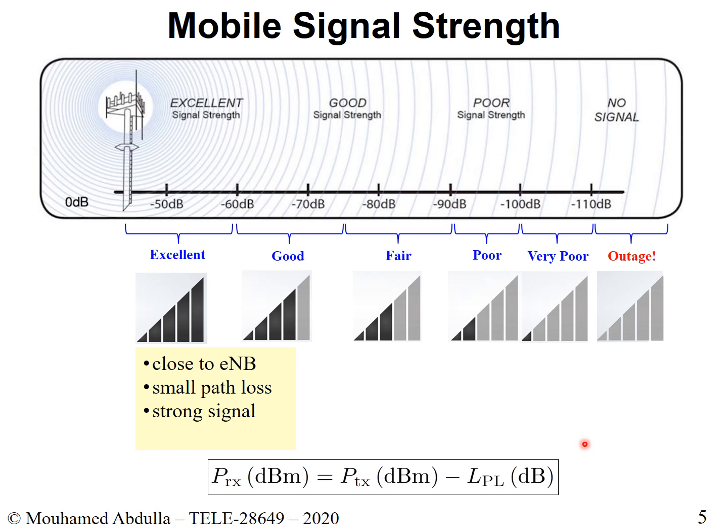Now, like we said before, if you want to include shadowing, that's also good, because you want to take into account at least the large scale component of fading. That's fine. You could simply add plus epsilon, and that would take care of your shadowing, and your epsilon will have a log normal distribution. That's how it's modeled. And in fact, in the log normal distribution of the epsilon, what is key in order to identify your shadowing is really the variance of your shadowing.